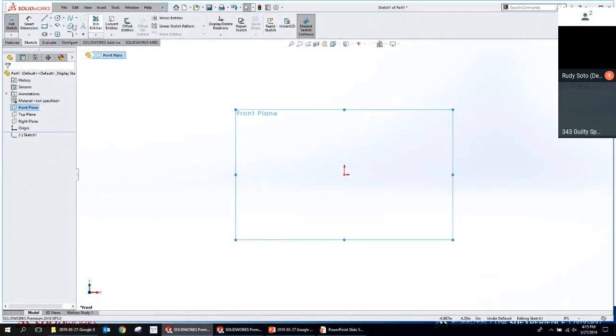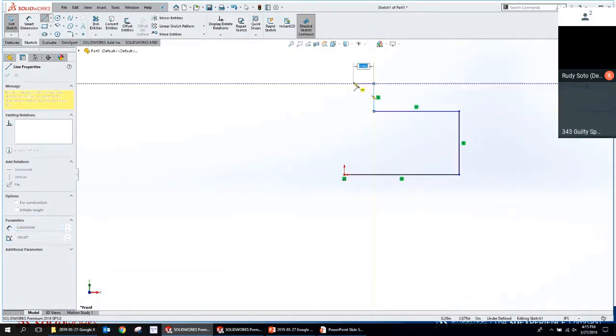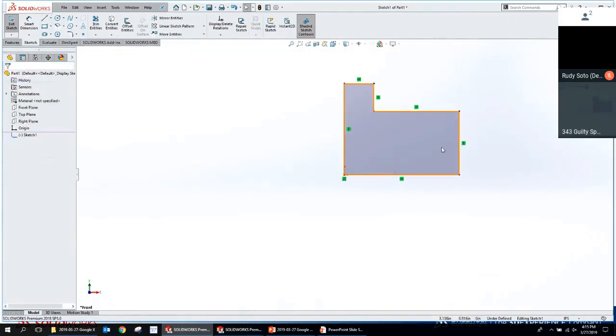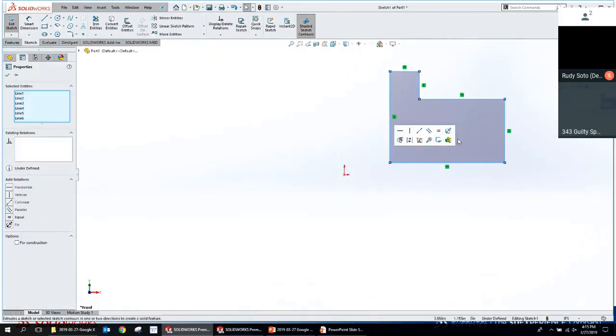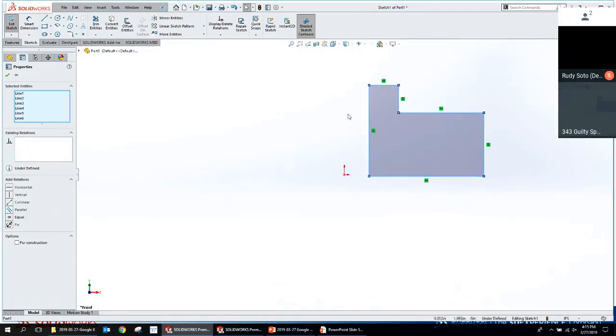What shaded sketch contours does is, whenever I create some type of sketch geometry here and then close it off, the geometry becomes shaded. The benefit of this is that it moves kind of like an instant block. I can grab in here and drag to move this around. But the downside is that you can't do drag commands for sketch relationships.